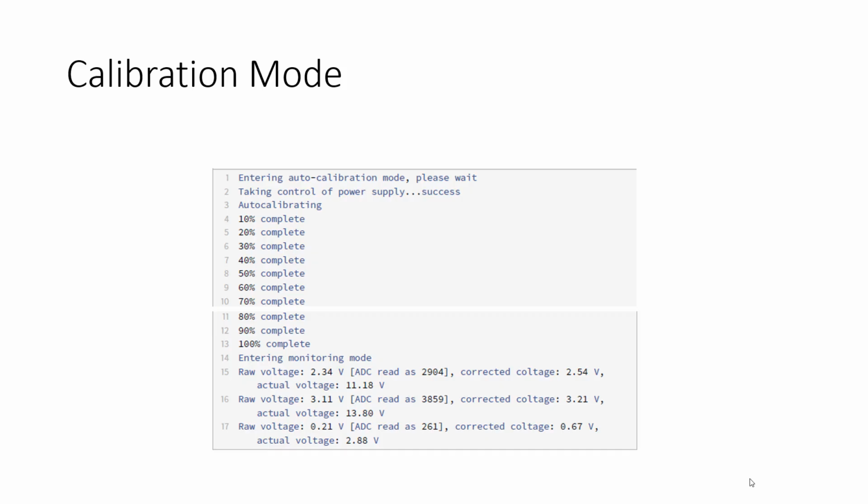I think the first time we did this, we were using something really low, and it took forever to get all the way through that range. I think last year we relaxed it to 50 millivolts, whatever it says in the lab sheet. But the increment is how much you're going to increase the voltage with each step. And you might say, well, come on, man, it should go pretty fast, right? I mean, it's the 200 megahertz chip. It's probably a millisecond to get through that range?